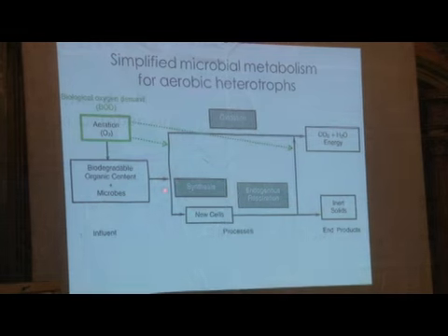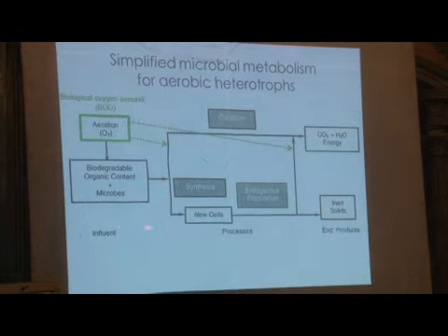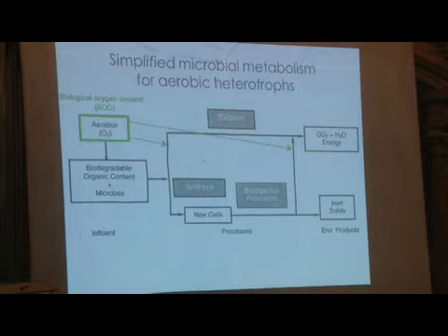At that moment, oxygen will only be consumed for the oxidation of carbon. Part will go to new cells. This is assimilation, we call it synthesis of cells, and this does not consume oxygen. Now, this is in detail what happens over these 5 days. Here, you see log colony forming units per ml. This is the concentration of bacteria.